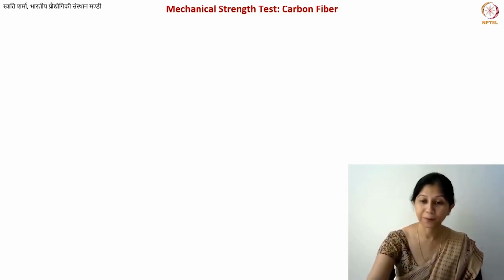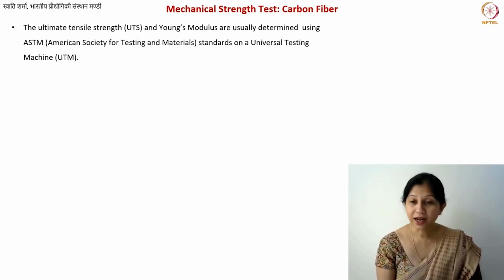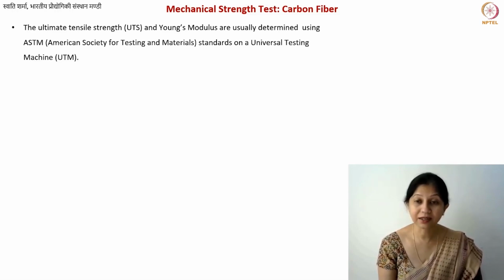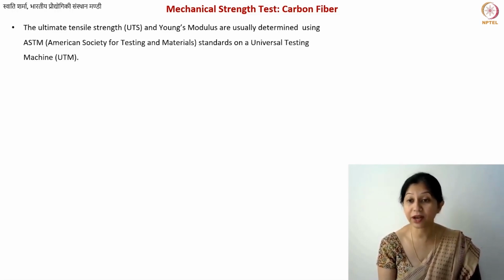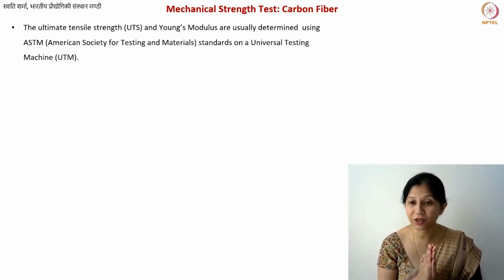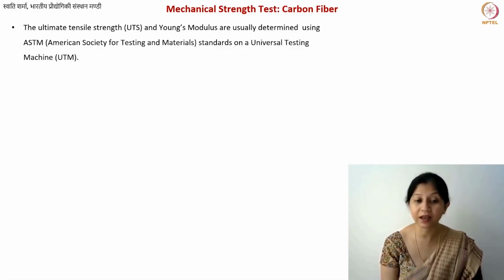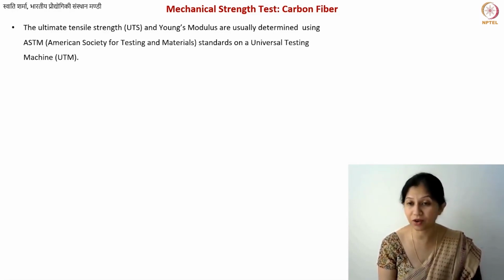At lab scale, these tests are relatively simple. In fact, those who have done their bachelor's in mechanical engineering may have already performed these kinds of tests in the lab. You will typically take, let's say, one mild steel rod, and then you will use a setup known as the Universal Testing Machine, or UTM. That is the common name, but there are also related instruments, and there are several in-house instruments also. So the name is not that important.